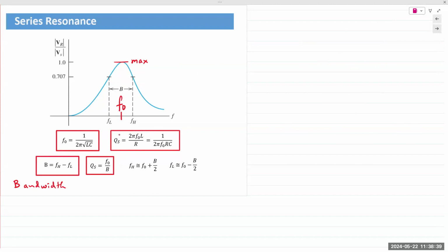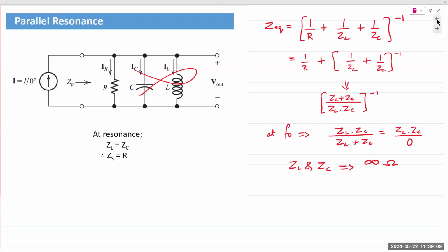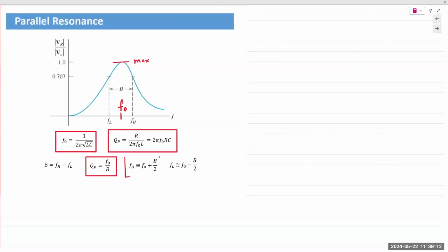Okay. If the quality of this filter circuit is larger, let's say if Q is much, much larger than, say, 5 or 6 or 10, then the curve may be symmetrical around the resonant frequency. And if it's symmetrical, then we can state that F0 is probably halfway between the two frequencies. But that's not always the case.